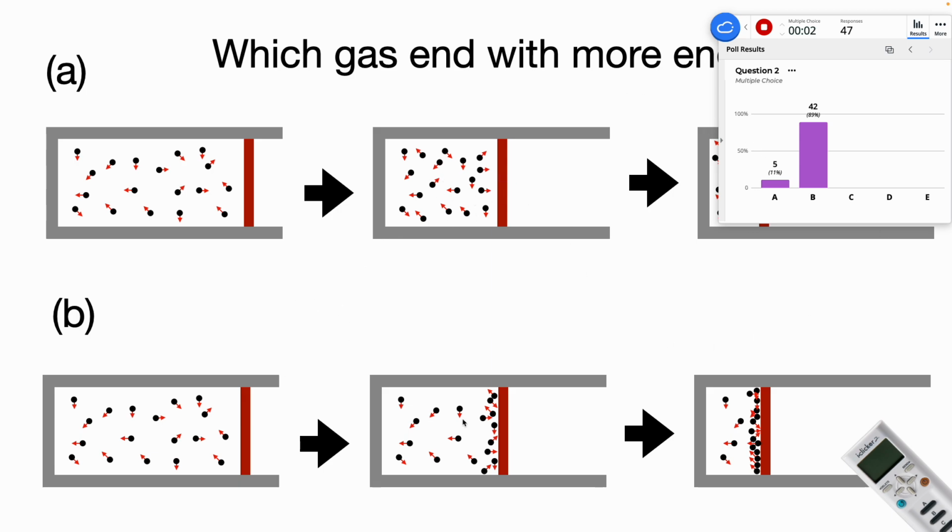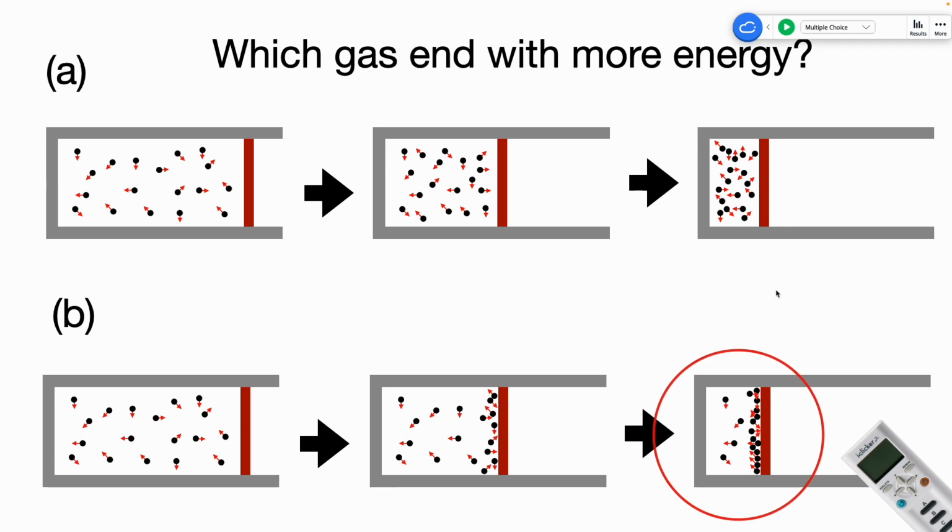At every stage down here, the pressure on the piston will be higher than with slow pushing because the gas is accumulating here. There's more gas hitting the wall compared to the slow pushing one. So at the end of the day, the way you push the piston will affect the amount of work you do to change its position. If you push it really fast, you will have to do more work. Okay? Any question? Good. Quasi-static? Not quasi-static.